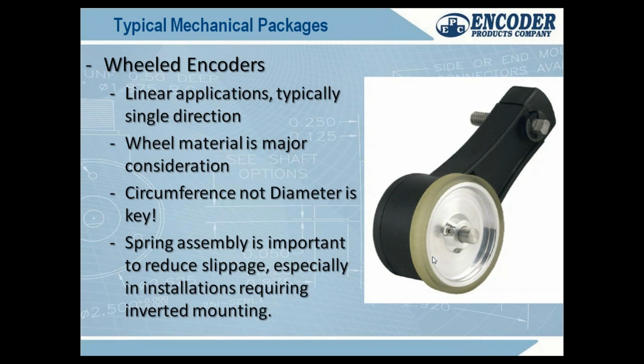These wheeled encoders will run on the product, they'll run on belts, and they'll give you a distance. How they do that is, this wheel here is 6 inches in circumference. So every rotation, one exact rotation, is exactly 6 inches of linear distance. If I have a 6,000 pulse encoder, a 6,000 line disc in here, I now have 1,000 lines per inch. So this encoder will give me a pulse every thousandth of an inch. That's the advantage. That's how you use a wheeled encoder.